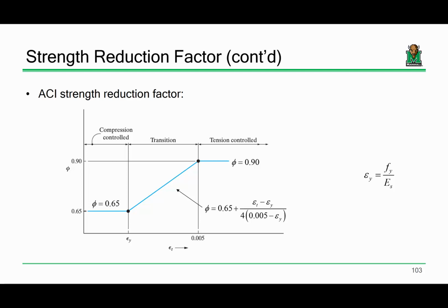Any questions? Do you ever have a situation where you have steel on top of the beam? Yes, absolutely. In fact, that's called a doubly reinforced beam. And in doubly reinforced beam analysis, the question that we have to ask is, does the compression steel yield? Because sometimes it does, sometimes it doesn't. Now, we include compression steel for a few reasons. First off, as we'll see later, you get a bump on long-term deflection performance. If you include compression steel, you actually improve your long-term deflections.